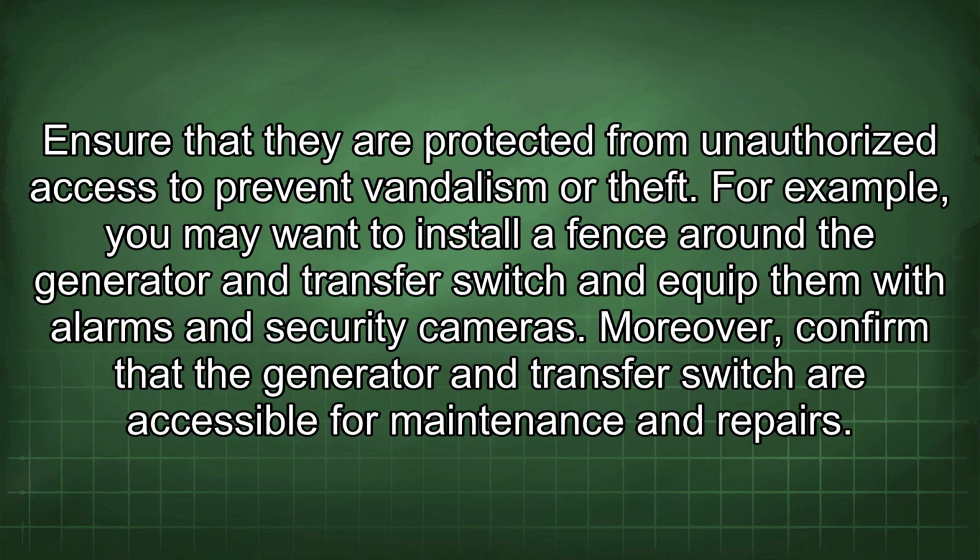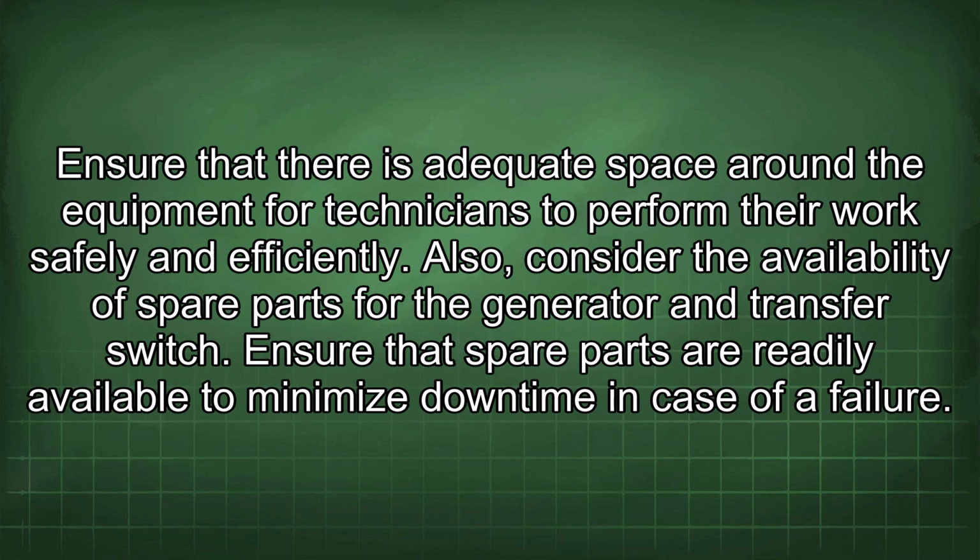Ensure that they are protected from unauthorized access to prevent vandalism or theft. For example, you may want to install a fence around the generator and transfer switch and equip them with alarms and security cameras. Moreover, confirm that the generator and transfer switch are accessible for maintenance and repairs. Ensure that there is adequate space around the equipment for technicians to perform their work safely and efficiently.